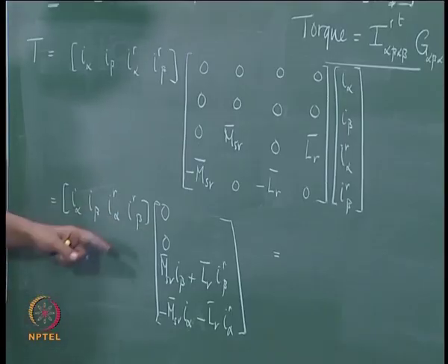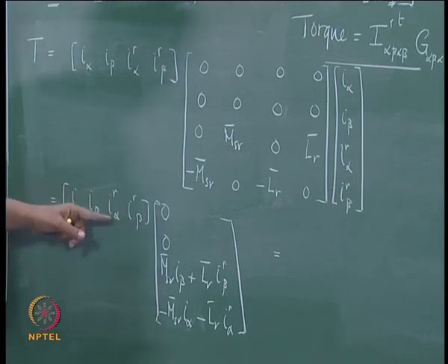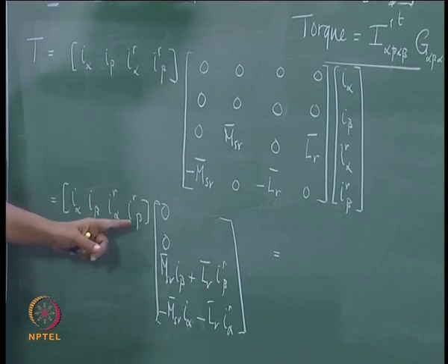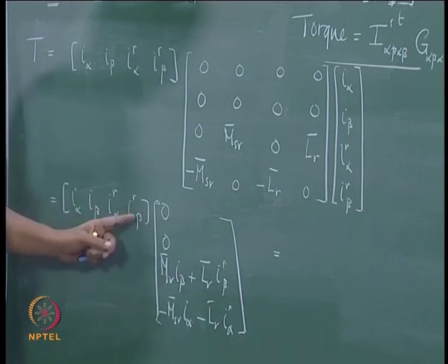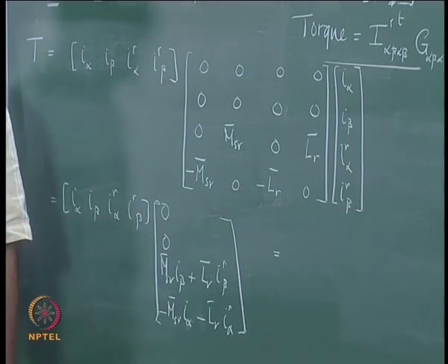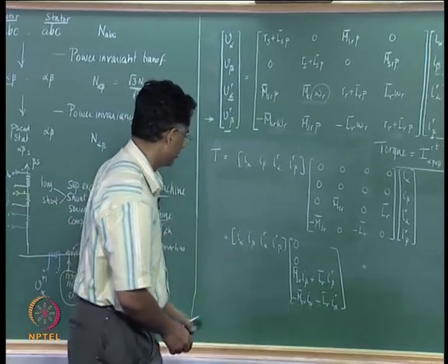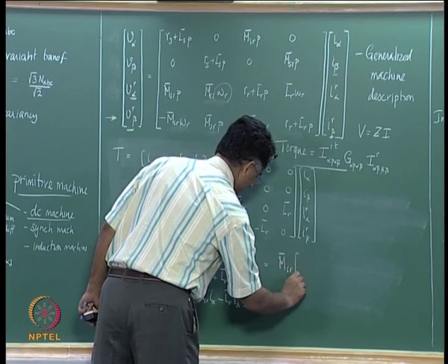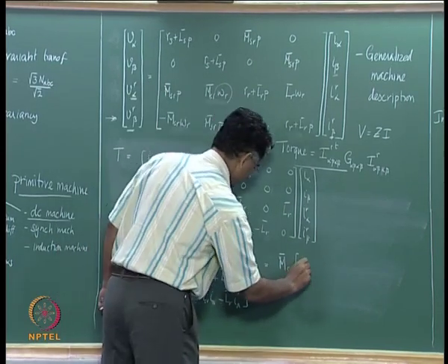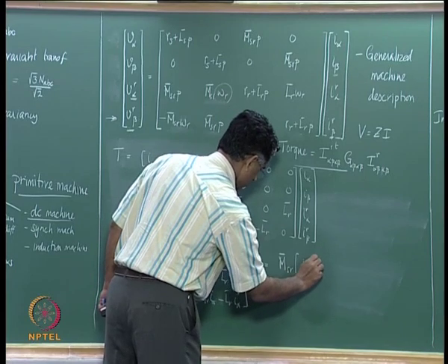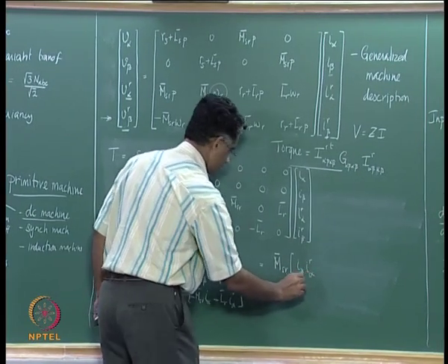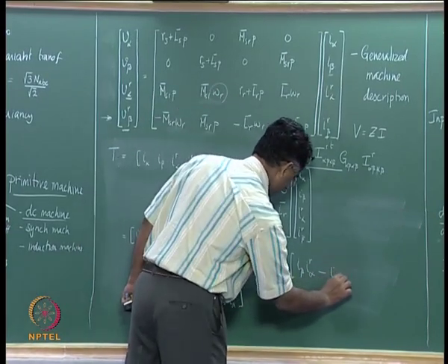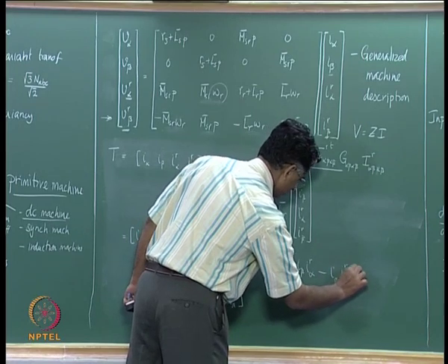In the next two terms you see I r alpha multiplying LR into I r beta. Similarly you have these two terms. So this term and this term contribute equal and opposite terms, and they simply nullify each other, and therefore the resultant is nothing but MSR bar multiplied by I beta into I r alpha minus I alpha into I r beta.